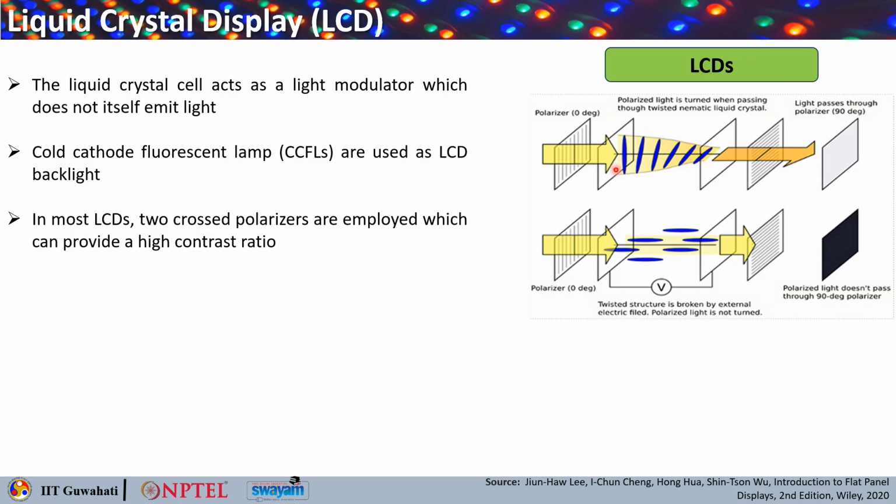So the twisted nematic liquid crystal allows the polarization of the light to get bent by 90 degrees, because of the nature of this crystal. So when light propagates through this material, its polarization axis gets rotated by 90 degrees, and then you again have another polarizer, which is a horizontal polarizer, or 90 degree polarizer. So this polarization can now pass through and you get a bright light.